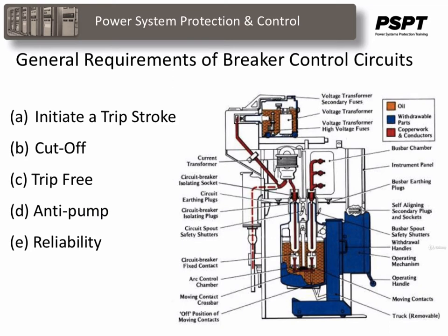Reliability. A circuit breaker is a protected device. It will be called upon to open faulty circuits infrequently. However, while it may stand inoperative for a long period of time, it must be relied upon to operate correctly in time of trouble. Reliability for such a protective device is essential. For this reason, a battery supply is always used to provide the tripping power and in most cases the closing power for a breaker. The control circuits usually have a separate trip and close bus.